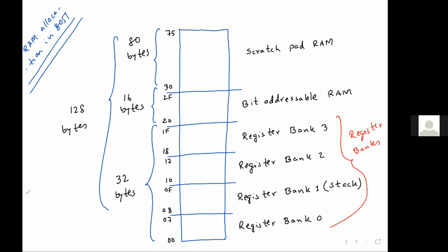And of course, you remember how we select register bank using RS0 and RS1. So using these 2 bits in your PSW register, we can select which register bank we want to access. And while we were discussing your flag register, if you go back to that table, you will see the addresses are exactly the same as the addresses I've written over here. So exactly the same 8 bytes are provided to each bank, and this is how your entire 128 bytes is distributed within the RAM. So if there is any question, you can ask now.